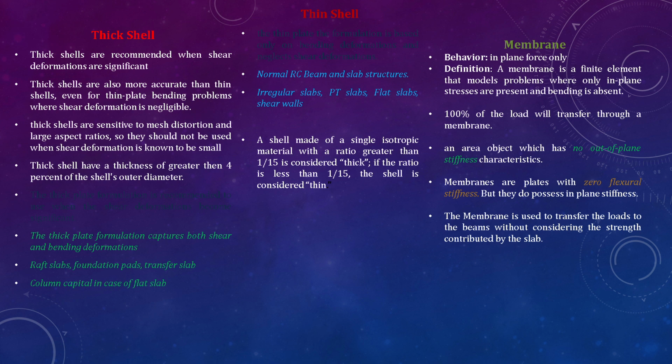If we have to choose between the two kinds of elements, thick cells and thin cells, thick cells will define the bending moment problem more accurately. Here, the change of shear deformation or the change of the shear stress can be calculated more meticulously.